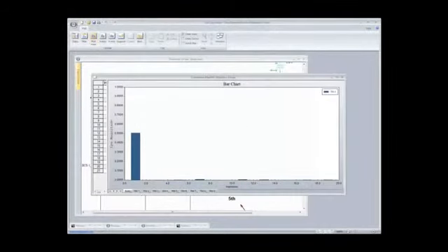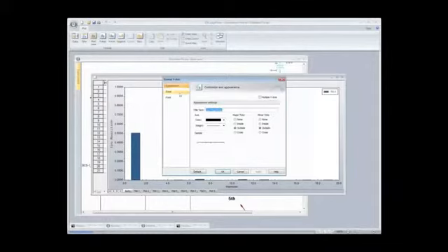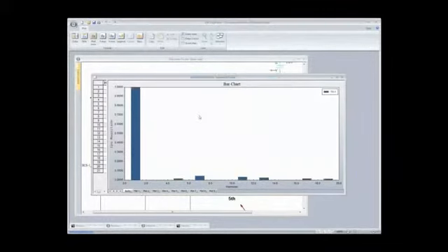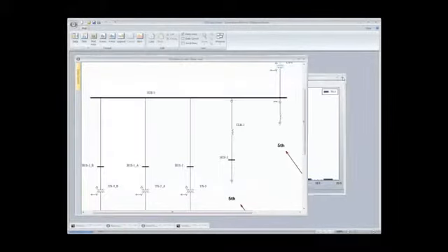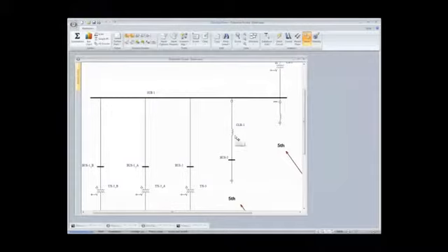If I now look at the current going through the transformer, I'll see that most of the 5th, now let me scoot this scale up a little bit, so 0.2 maybe. So most of the fifth has been absorbed, because the fifth was up here, but most of it's being absorbed by the filter, but it's still doing current division. Some of the fifth is still getting out slightly, and then there's your 7, 11, and your 13. But the filter itself will absorb some of the higher frequency harmonics when you apply it. And that comes into play when you specify it.